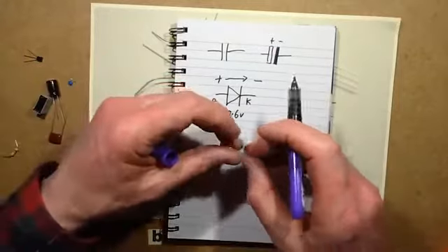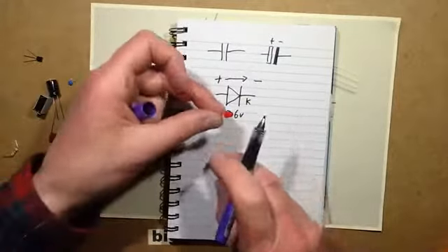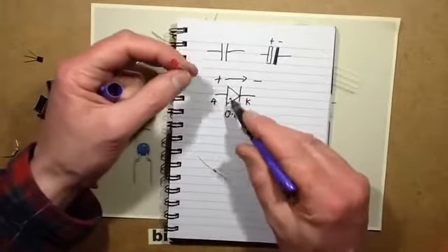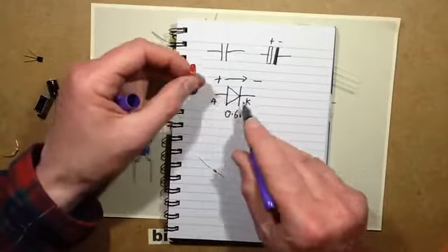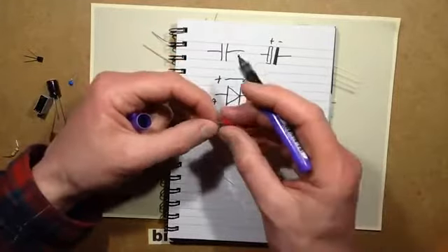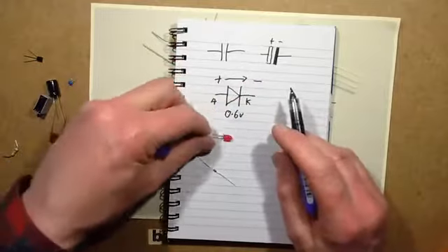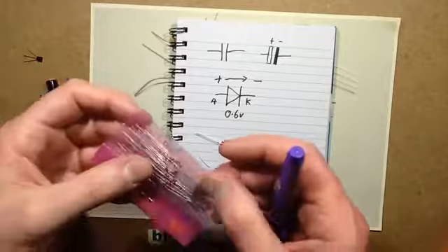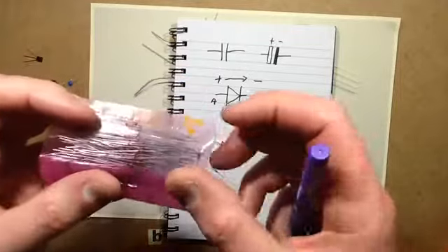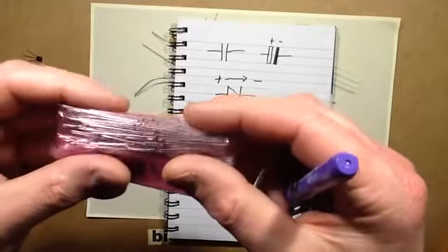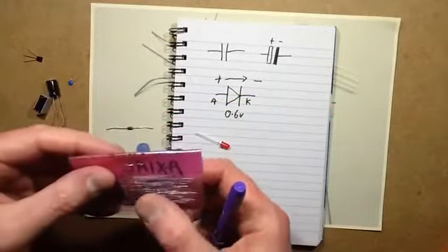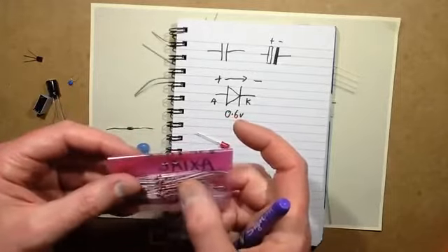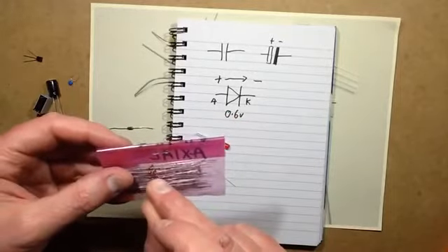The light emitting diode, our favourite type of diode really, is a diode junction that is optimized. It behaves in a way like a normal diode, but when it's forward biased, when the current's flowing through it, it emits light. And the very first LEDs were actually, here's some here, they look just like the 1N4148. These are actually LEDs. They look just like ordinary glass diodes, but these are really vintage LEDs, and when you actually pass current through them in the correct direction, a little red dot glows inside them.